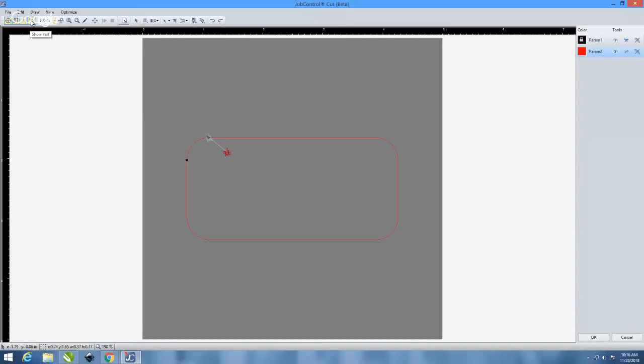Next, you can show, usually, John, if you're cutting a piece of acrylic and the laser starts on the line, you have that tiny little blob. So you want to start it from coming in, right? Yeah. So Anthony, that's under draw, and you can do lead in there. So you just go up on the top menu, click draw.